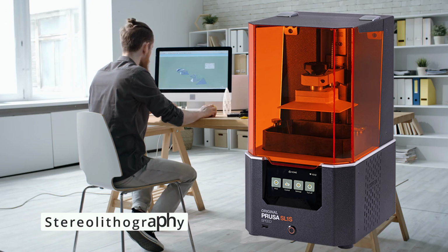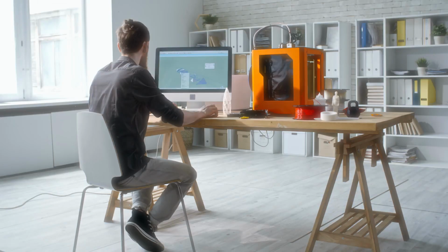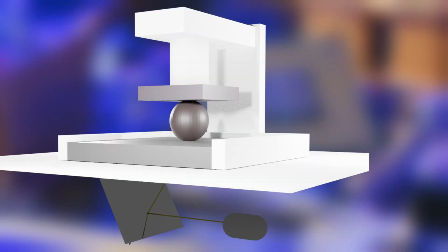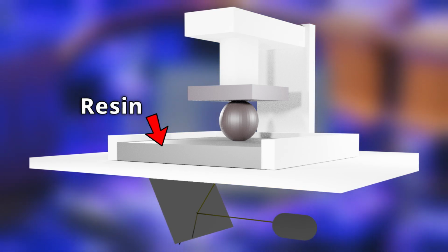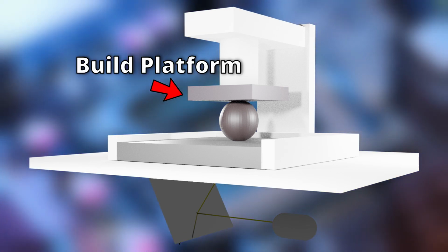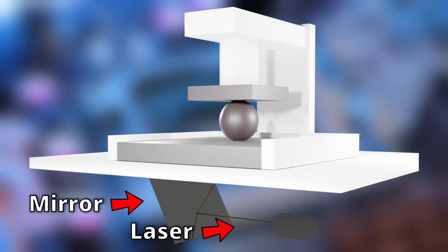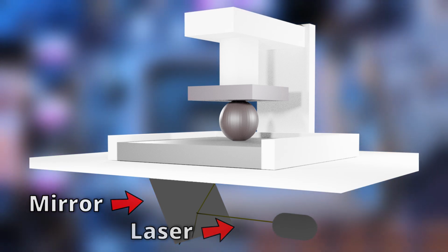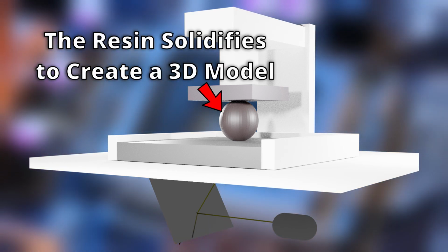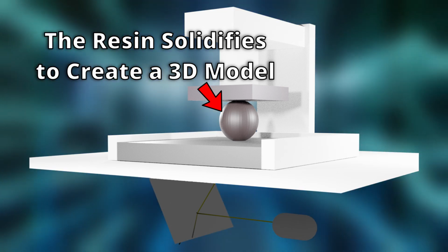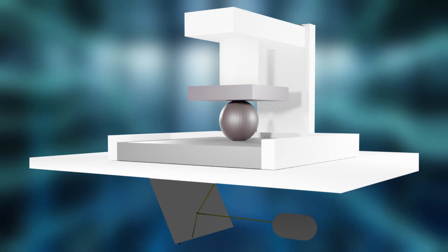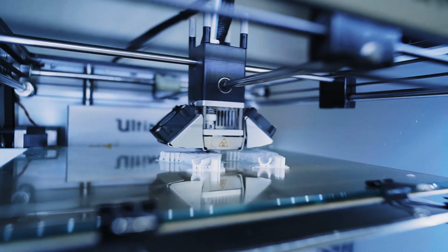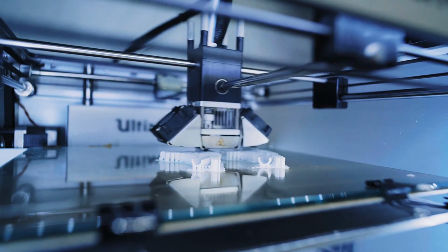Stereolithography or SLA is a type of 3D printing technology that uses a laser to harden resins into plastics layer by layer to build an object. Resin looks like liquid. It is poured into the container of the printer. Once the resin is poured in, the build platform lowers until it submerges in the resin. Then, a laser beam is directed onto the surface of the liquid resin, which is sensitive to light. The laser traces a cross-section of the digital model onto the surface of the resin, curing and solidifying it. The build platform then descends by a precise amount, and a fresh new layer of liquid resin is spread on top. This process is repeated layer by layer until the entire object is completed.